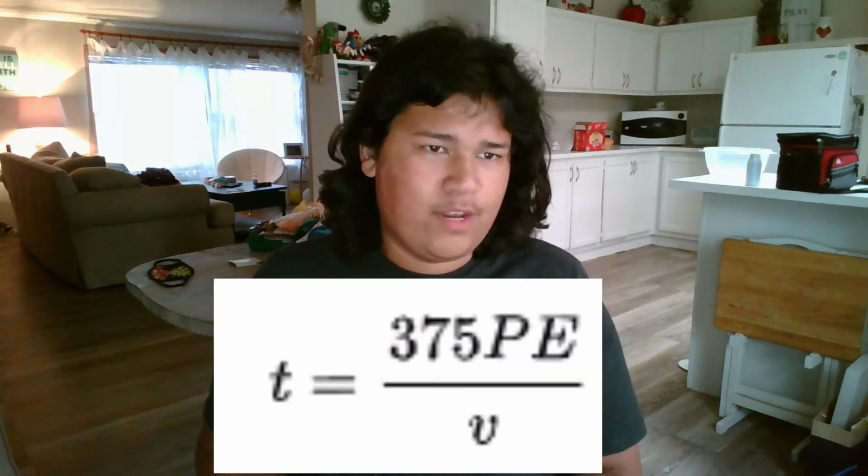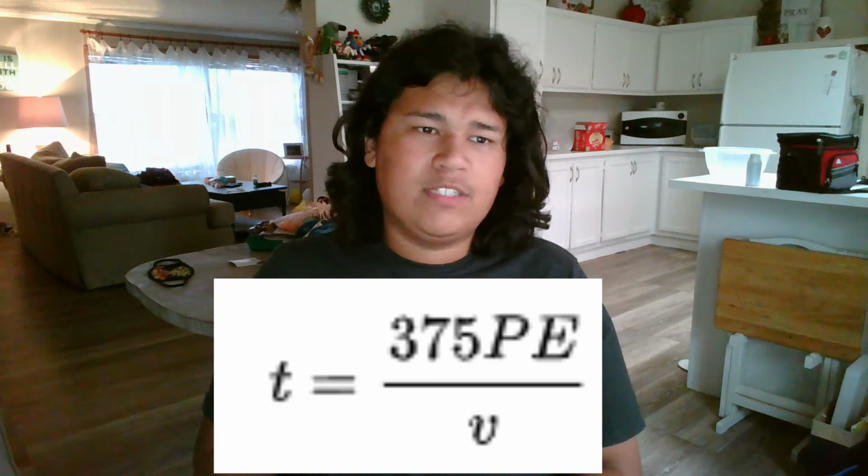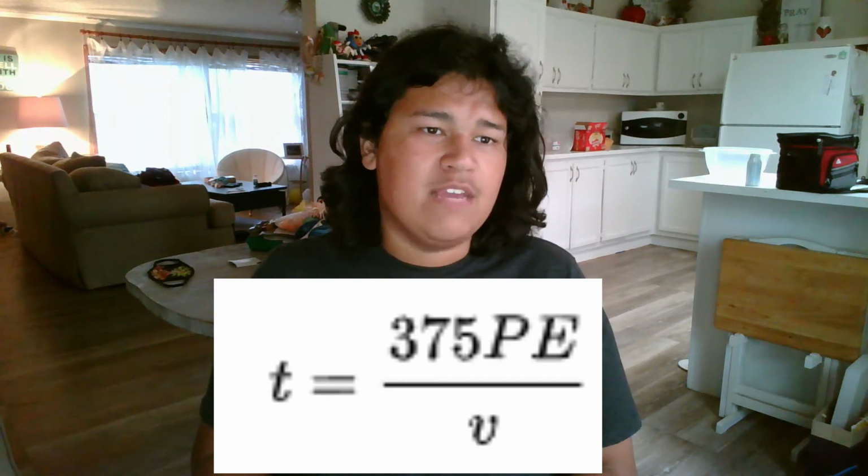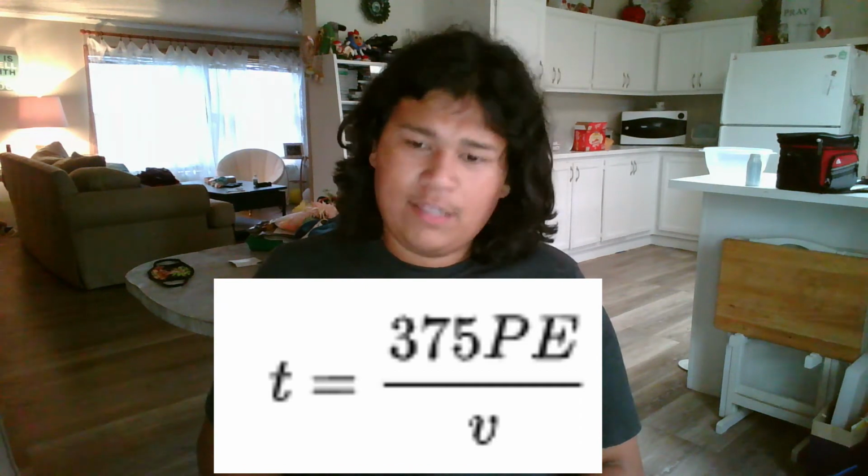For a diesel hydraulic locomotive, the starting tractive effort is affected by the stall torque of the torque converter, which is a type of fluid coupling that transfers rotating power from a prime mover like an internal combustion engine to a rotating driven load, as well as gearing, wheel diameter and locomotive weight. The equation for this is tractive effort equals 375 times the power in horsepower times the efficiency divided by velocity. And that one is not as hard.